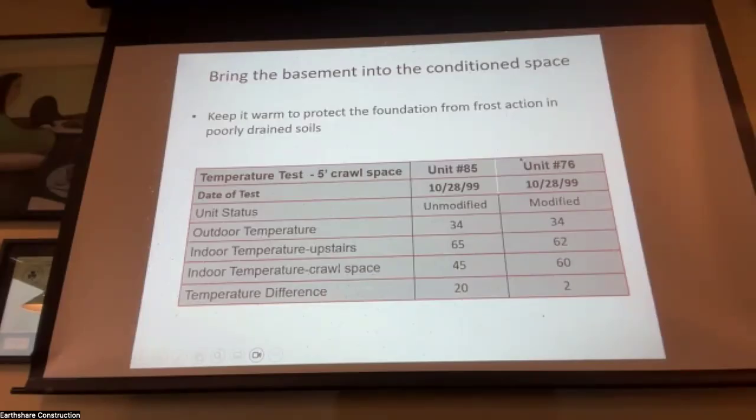Well, no, because that's the same thing, because you're talking about pressurizing the home at cubic feet per minute. Why would you do an air change test of how much air change per hour is happening in that space? Because ACH depends on the ratio of volume and doesn't take into account the ratio of volume to surface area. If you have a sphere, the ratio of volume to surface area is 1.